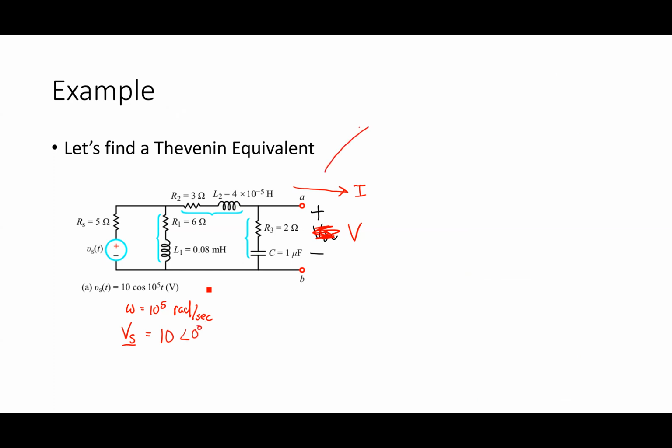So I've got to convert the circuit over into the phasor domain, and I write V sub S with that bar. I usually write them as capitals. I'm going to label everything symbolically. Honestly, I don't find it particularly useful to use numbers. I know you like to use numbers; it freaks you out to use variables. But I can get a lot more intuition about what's going on with variables, whereas numbers are just numbers. And I can check my reasoning if I keep them symbolically.